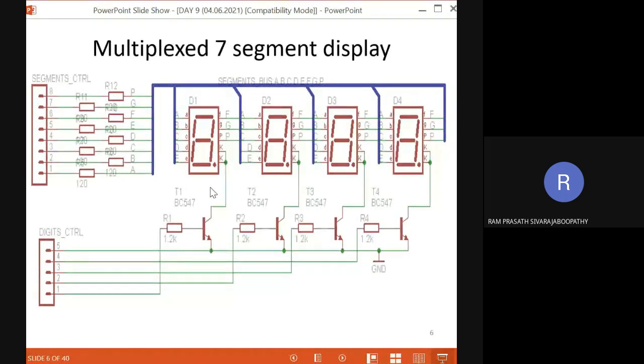Fine. It happens in the timing of milliseconds. It is happening with the time of milliseconds. It's not happening for seconds. In the program, it executes in microsecond timing itself. So what I am doing is waiting for some time by having some delay. When we are doing simulation, we need not go for the delay option, because our simulator is running very slow, but for a real-time application, you have to introduce a delay.